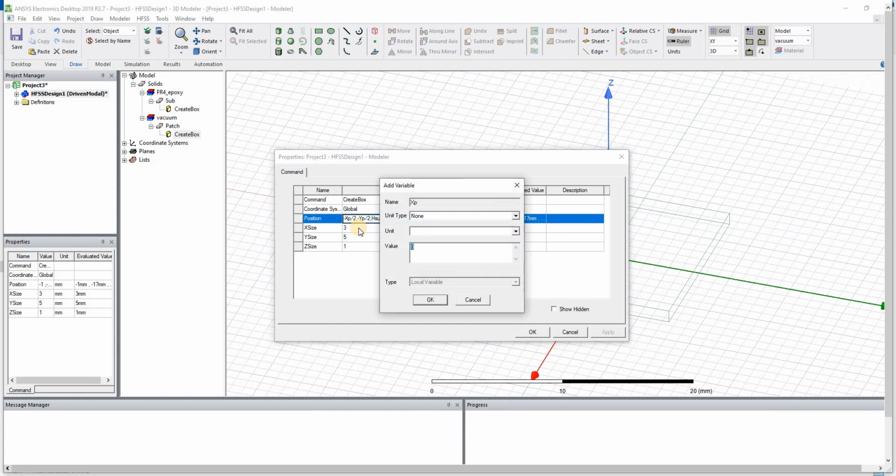So let's say for 10 gigahertz the lambda is going to be 30 millimeter, and lambda over 2 is going to be 15 millimeter, but the substrate permittivity, epsilon effective, is going to be 4.4, and the length is going to be lambda over square root of epsilon effective, or epsilon r, which is about lambda over 4.